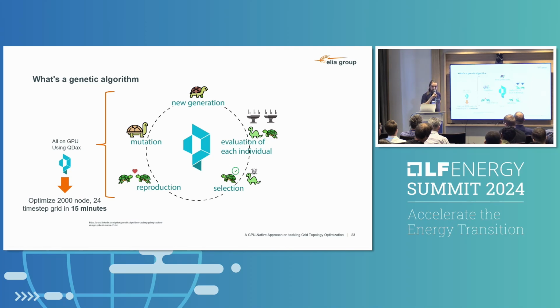So the question was, do we check for sensitivities, with the example of if load or generation changed slightly, do the topologies still hold? No, actually not. We do not compute any sensitivities. We evaluate load flow computations. So what we do is have a certain error band. We put a conservative limit.